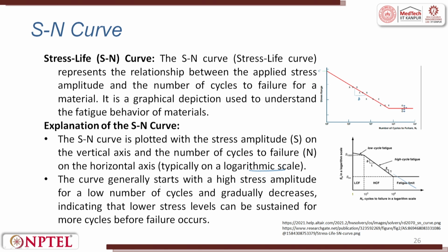The curve generally starts with high stress amplitude for a lower number of cycles and gradually decreases, indicating that low stress levels can be sustained for more cycles before failure could occur.